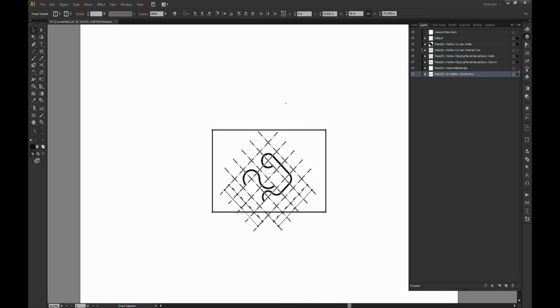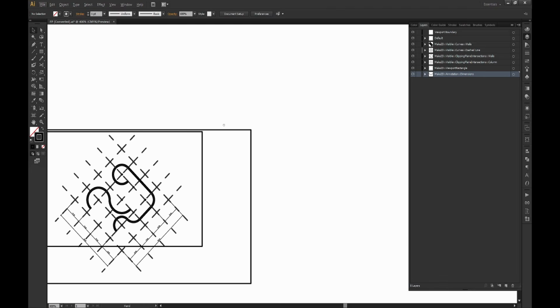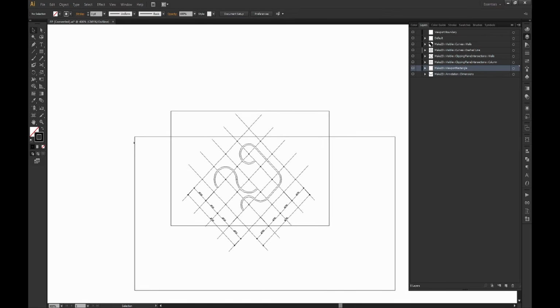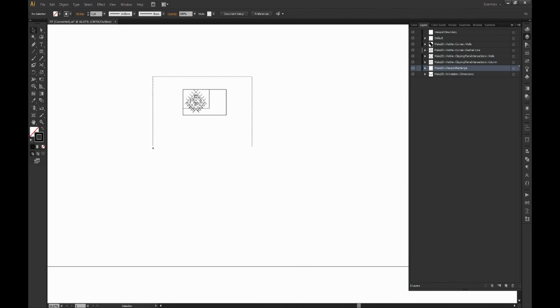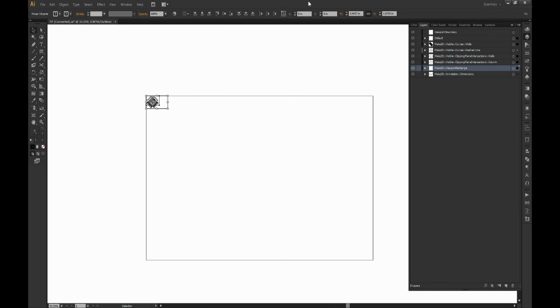That's one way. The other way is to do it by hand, which is up to you. It's not as accurate, but it's still pretty accurate. What I would do is move this. This is the viewport rectangle that we also want. If I press Control Y, it's easier to snap to things because it's just an outline view. If I move these two together to the corner up here, and I change my snap point to the top left, you see the top left?